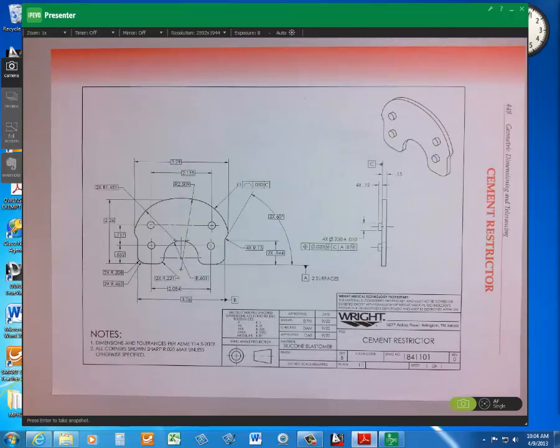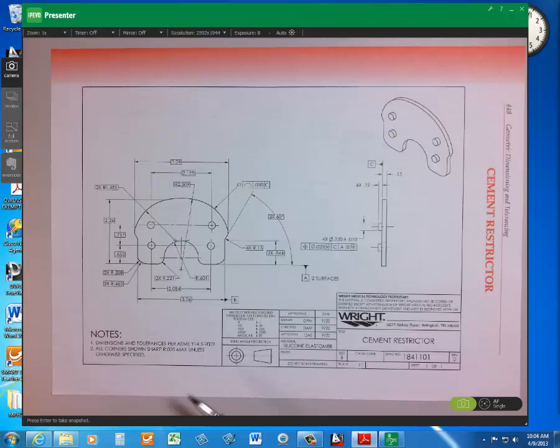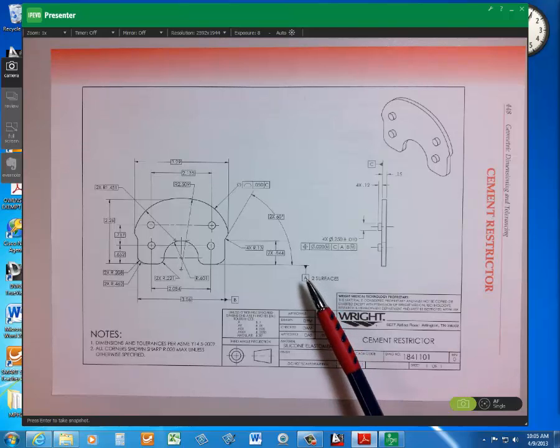All right, the 4 times 250. Okay, those are the little pins that are sticking out. It almost looks like a brake pad. Give the location dimensions from datum A and the location application relative to datum B. Okay? So the location dimensions from datum A. Datum A is the bottom edge. The lower features are located 0.652 basic from datum A.